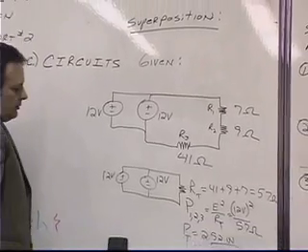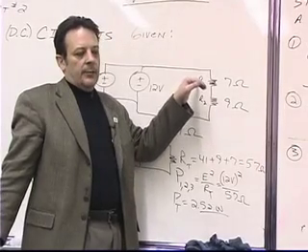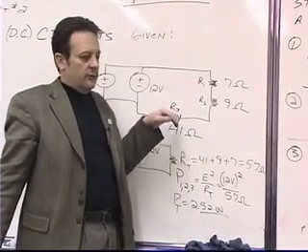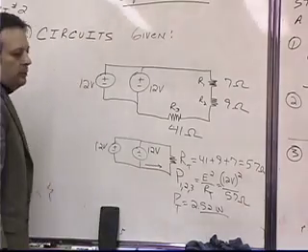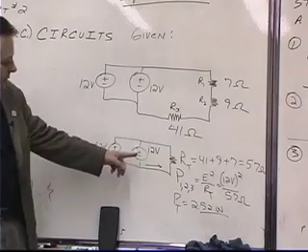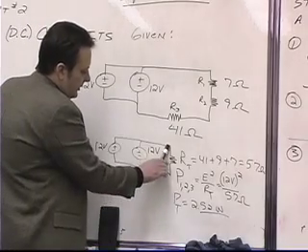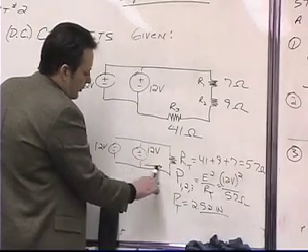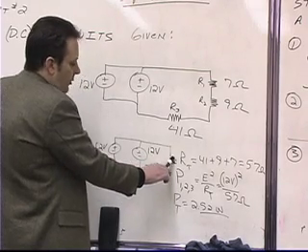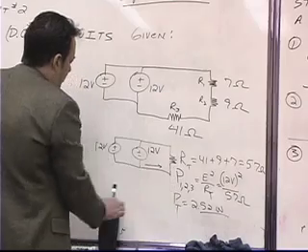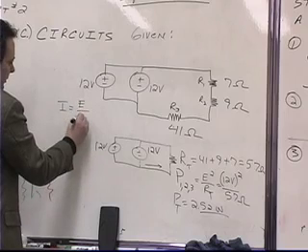if we did calculate the current so that we could come back and calculate the power distribution in each one of these resistors, what would the current be flowing in that loop right there? We know that these two are in parallel, right? Because it'd be fair to say that this forms a closed loop. So if this is 12 volts, this has to be 12 volts, right? So what would be the current flowing through our total resistance? Would the current be equal to the voltage divided by the resistance?